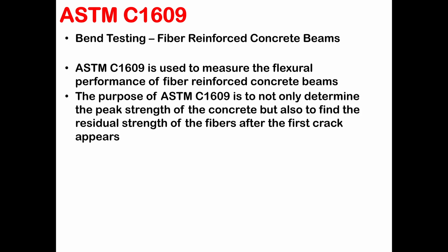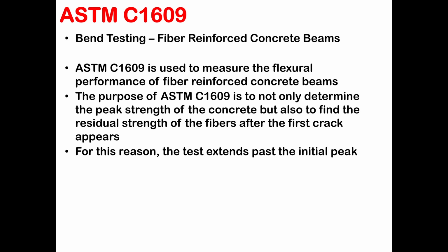The purpose of this standard is not only to determine the peak strength of the concrete, but also to find the residual strength of the fiber after the first crack appears, which is a very important element in concrete analysis in general.